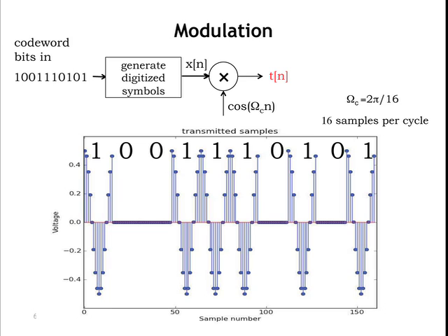A short burst of cosine. This is 16 samples long, and then 32 samples of 0, and then 48 samples of cosine, and so on. All right? So your loudspeaker is emitting power and then turning off, and emitting power and turning off. And this is what gets picked up by the microphone. So the microphone has to figure out, this is the particular case of an on-off signaling scheme, what's being sent.